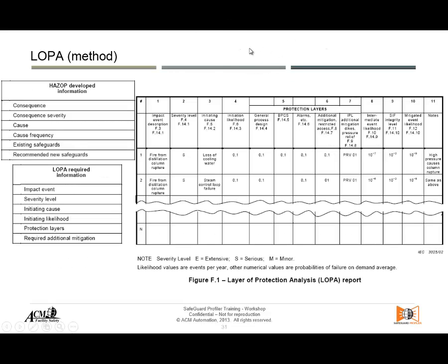This comes directly from IEC 61511 part 3. They show a table there, and you can build this table, for example, in an Excel spreadsheet. In there you will see all these columns, putting in order the initiating events or the causes, and then the protection layers, as you can see here, and then other modifiers sometimes, or conditional modifiers and enablers, so that they work out into the LOPA scenario.